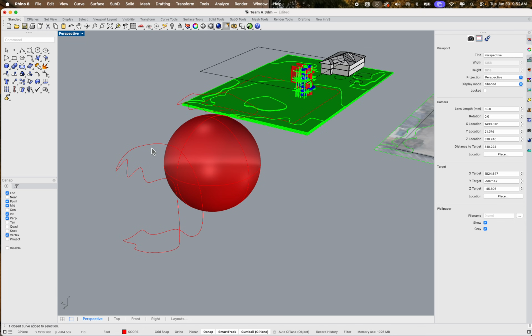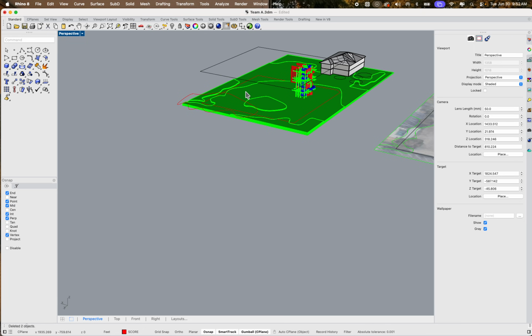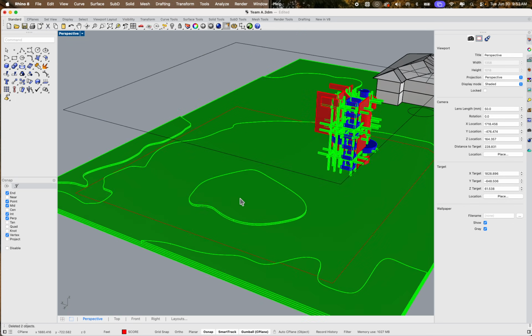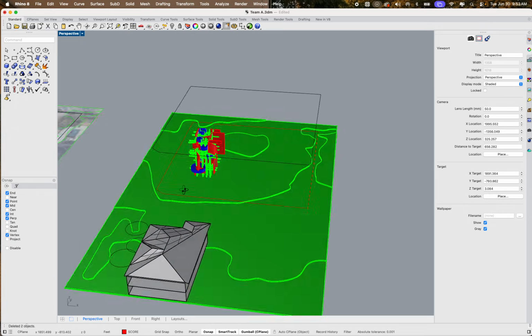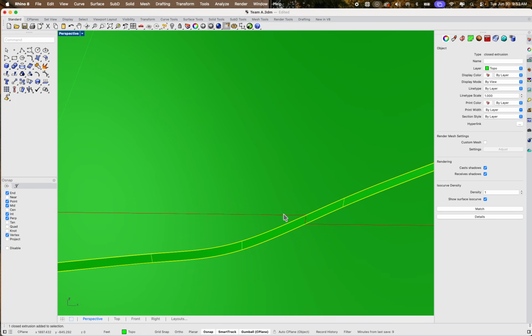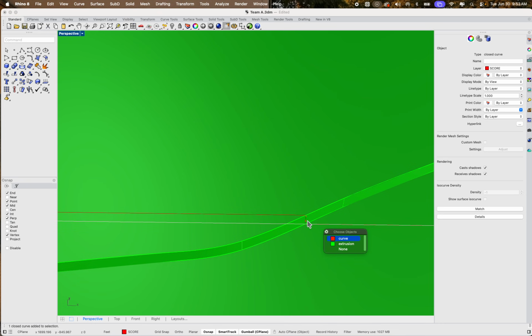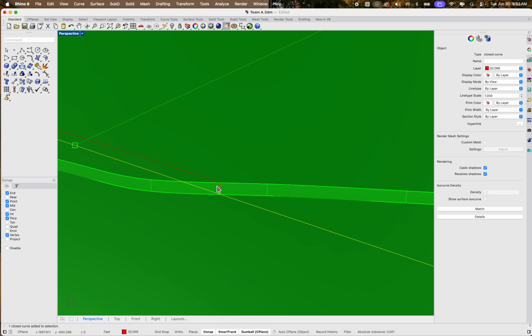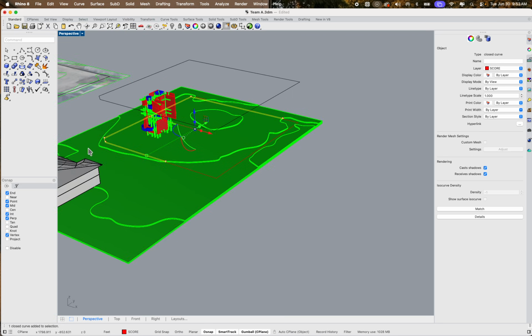Now that obviously doesn't come up a whole lot, but projecting onto a topography surface arguably comes up in every single project, right? So I didn't want to leave that tool out, because it's entirely useful when you need to go from one piece to another. As you can see with that curve, it's going to actually guide it. You'll see that it goes around this entire object.